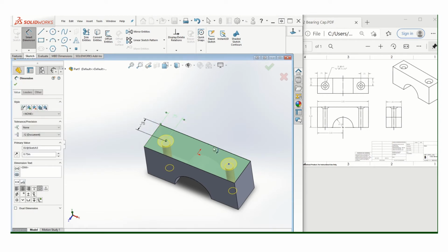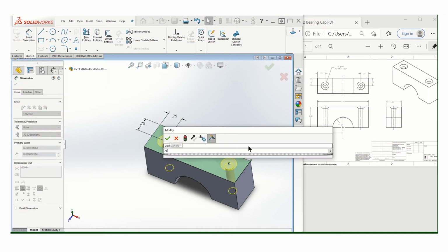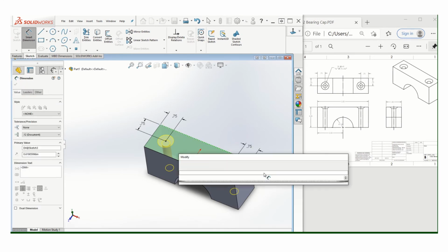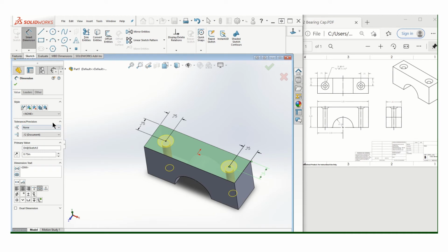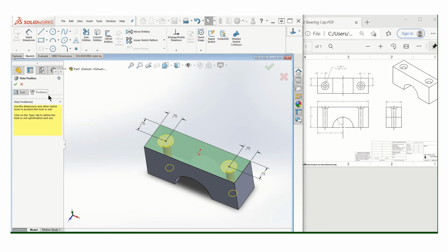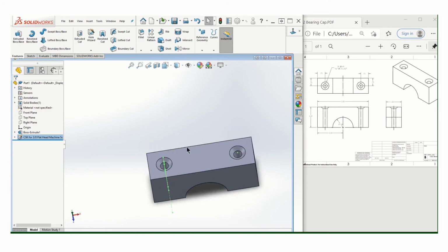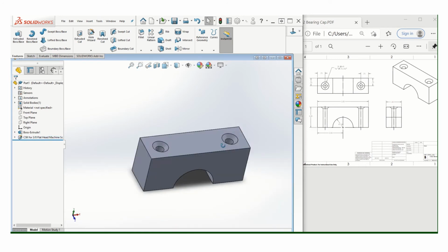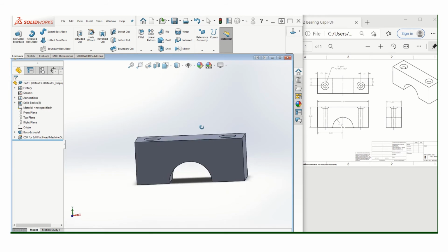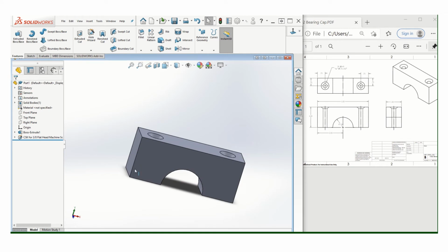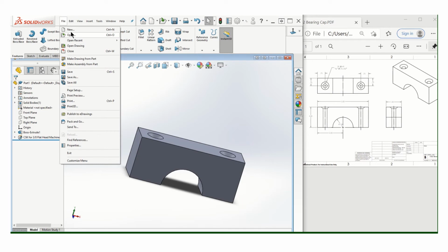Remember, these are just sketch dimensions. You should have everything done. Let's click on that and see. So that's how you do a countersink. Simple enough. Now remember, the holes have to go all the way through. The whole idea here is you'd put that fastener through and then bolt this to something else. So let's put that on a drawing sheet.